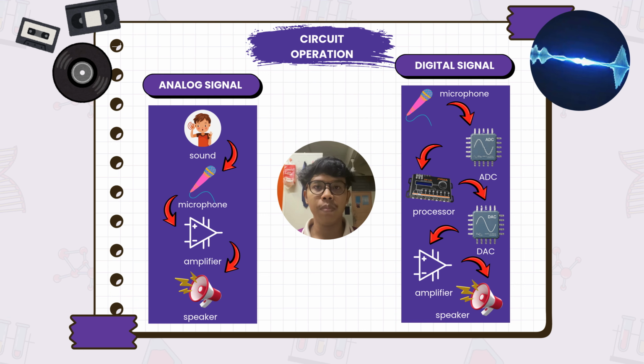Unlike the analog system, the digital system processes information using binary values, which are 0 and 1. The operation begins when the microphone receives sound and converts it into an analog electrical signal. Since the processor can only process digital data, the analog signal is first converted into binary data by an analog to digital converter or ADC. Next, the processor performs operations such as storing, filtering, or processing the digital information.